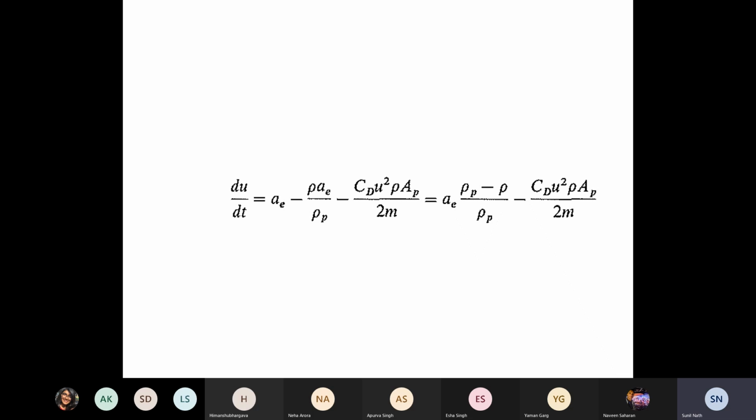All right. Now, this CD, of course, depends on the drag force. The one thing is that the drag force itself depends on velocity. You know that expression for the sphere, it was linearly dependent on the velocity, directly proportional to it. Now, that is a very idealized expression for a very low Reynolds number and only for a solid sphere. But one constant thing that is found from all experiments is that as the relative velocity between fluid and solid increases, the drag force always increases. It's an increasing function of this velocity.